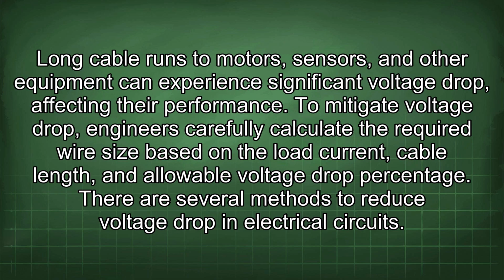To mitigate voltage drop, engineers carefully calculate the required wire size based on the load current, cable length, and allowable voltage drop percentage. There are several methods to reduce voltage drop in electrical circuits.